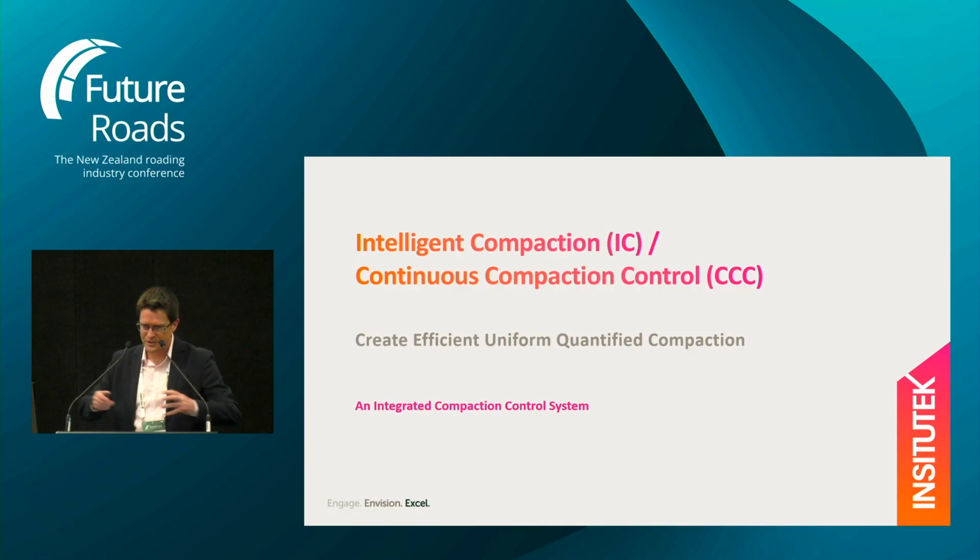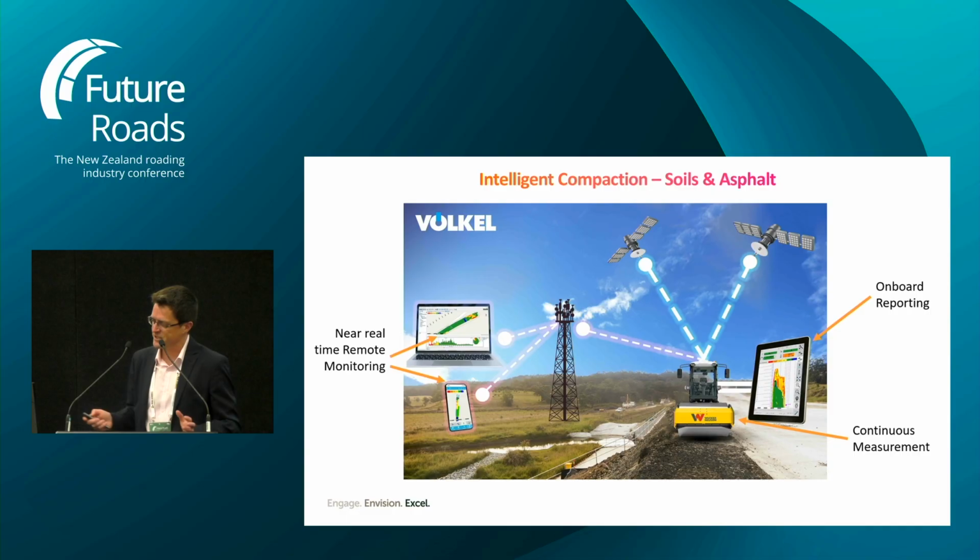Essentially what we're trying to do is to connect the in-situ testing methods with the rollers. So at its most basic, what we're talking about is instrumentation mounted on the rollers, and we've got feedback for the operators, so real-time feedback for the operators, and then we've also got the potential to do real-time monitoring. Imagine you have got two rollers, they're connected together. The data is being synced between the roller operators every 15 seconds, and also somebody who's working remotely, for example, a supervisor, right? So they can see what's going on site as well.